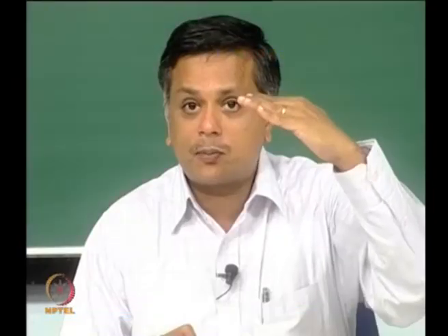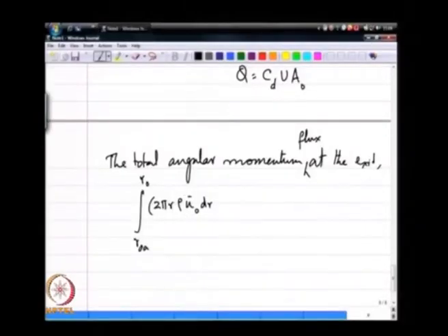Okay, so the mass is being brought out of the nozzle by the axial velocity, and rho u0 bar times 2 pi r dr is like a differential cross sectional area at a radius r. This is the actual differential mass flow rate coming out of a thin slice dr wide at some radial location r.